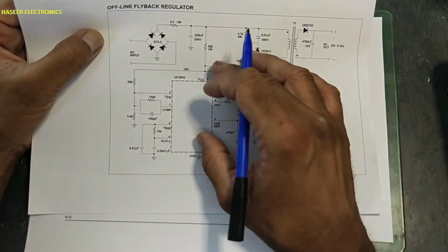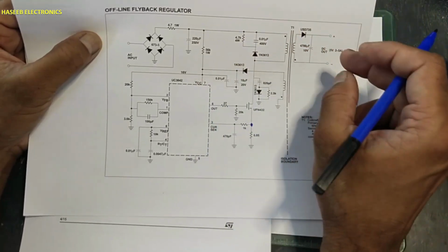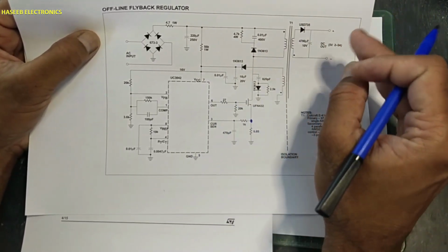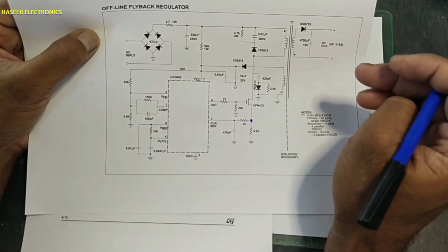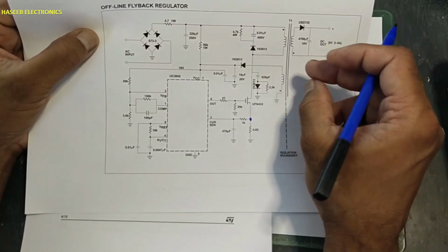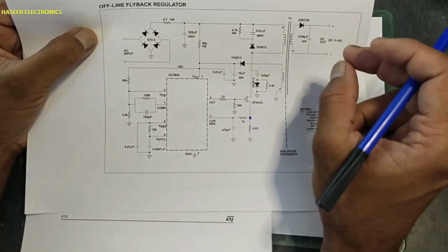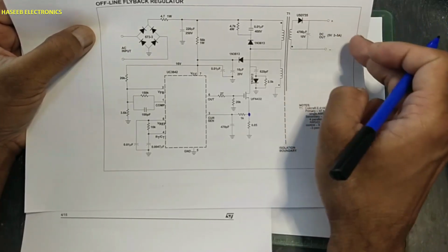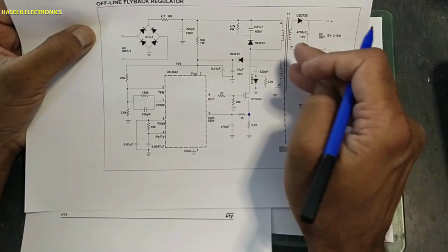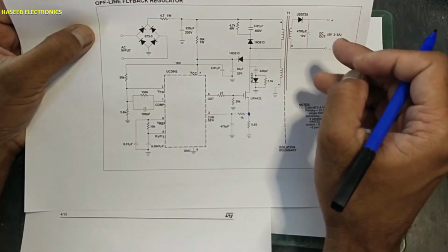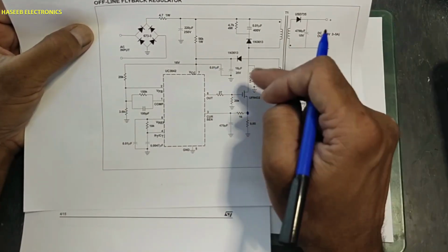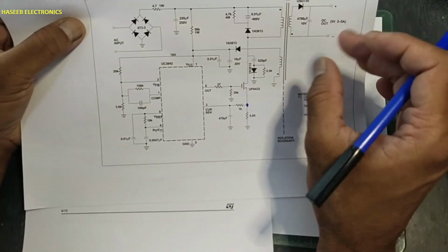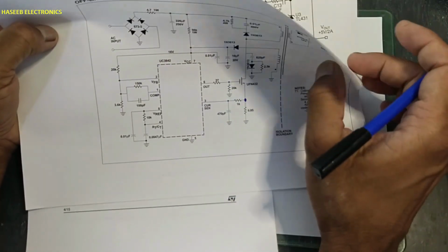The drawback in this circuit is that it provides approximately 5% regulation of the load voltage, and it has a slow response to detecting load transitions. If there is no load, it works normally and regulates the voltage, but at a sudden load, it will not sense that load immediately. So it has a slow response.